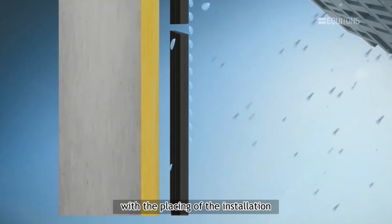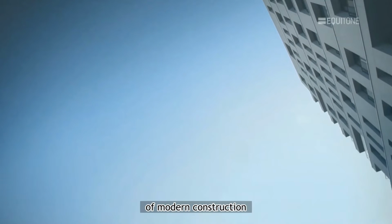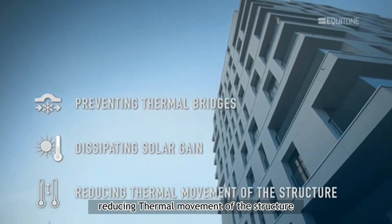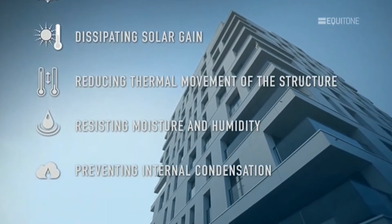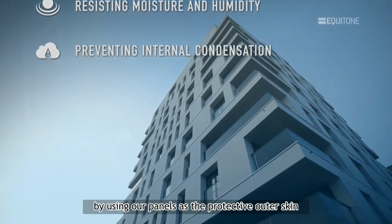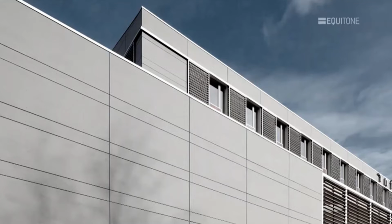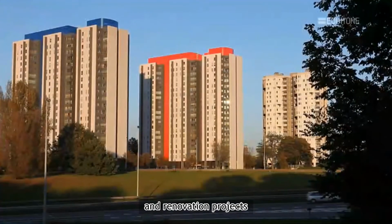With the placing of the insulation on the outer face of the structure, rain screen also meets the challenges of modern construction in terms of preventing thermal bridges, dissipating solar gain, reducing thermal movement of the structure, resisting moisture and humidity, and preventing internal condensation. By using our panels as the protective outer skin, we also give the buildings the added feature of looking good. Rain screen is ideal for use in both new buildings and renovation projects.